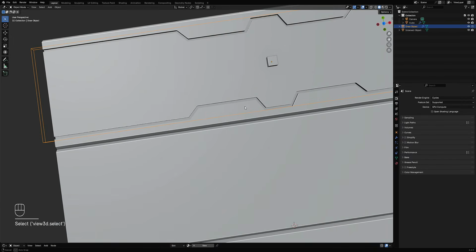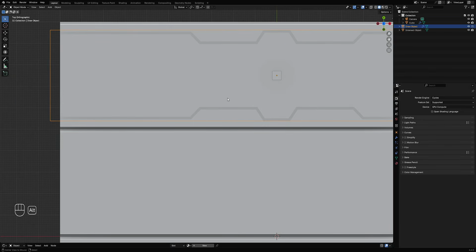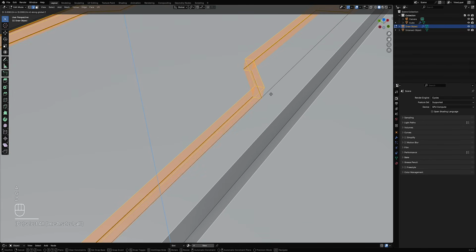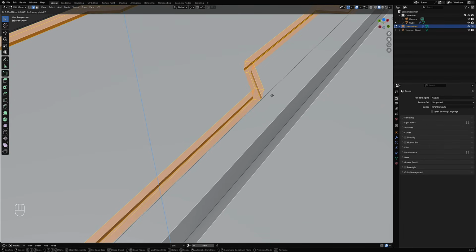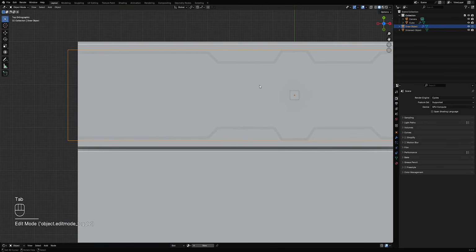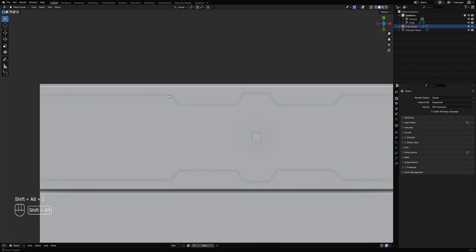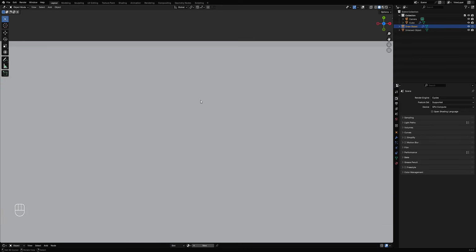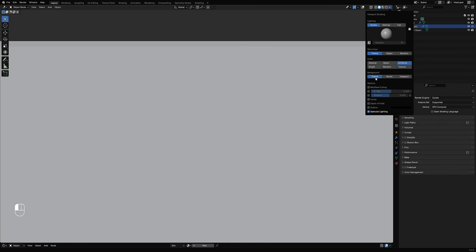And probably to make the details pop out, because in the last videos I've told you that you need to kind of inset to make the baking process see these details, because without those it will only see this without cavity and outline. It can't see the detail if it's just being extruded straight up or down. So you need to either bevel or inset with some margin, cavity, outline.